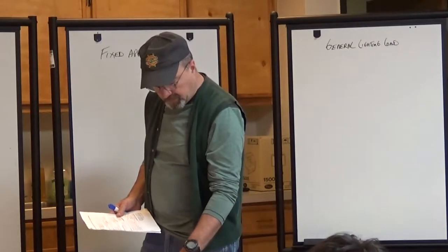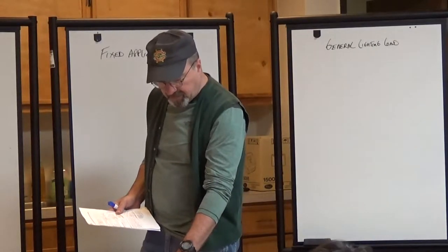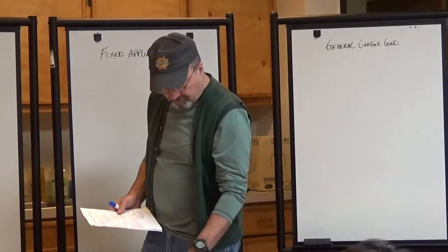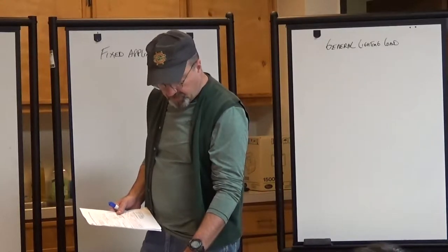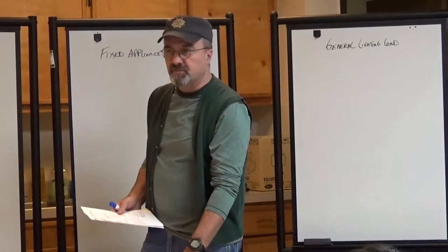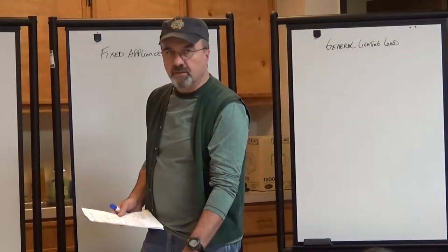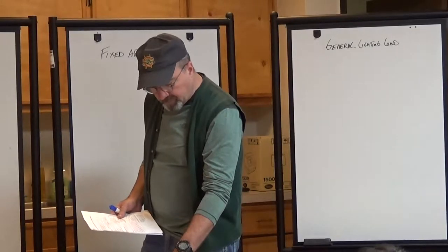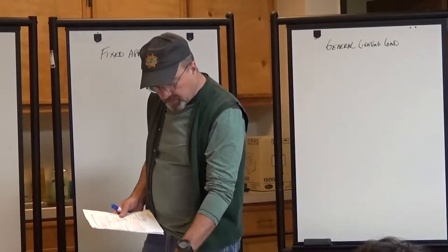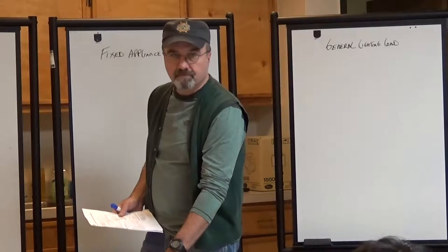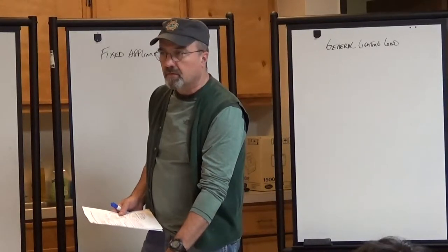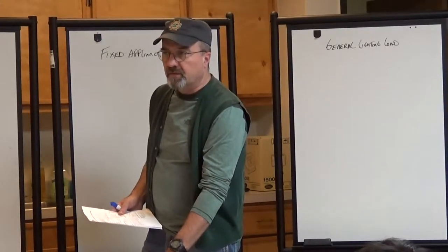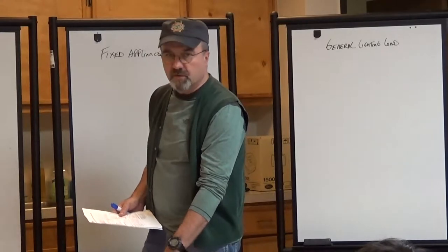You have banks, churches, clubs, armories, restaurants, schools, stores. We're interested in dwelling units. The VA per square foot for dwelling units, does anybody find that? And what is that? 3 VA per square foot.